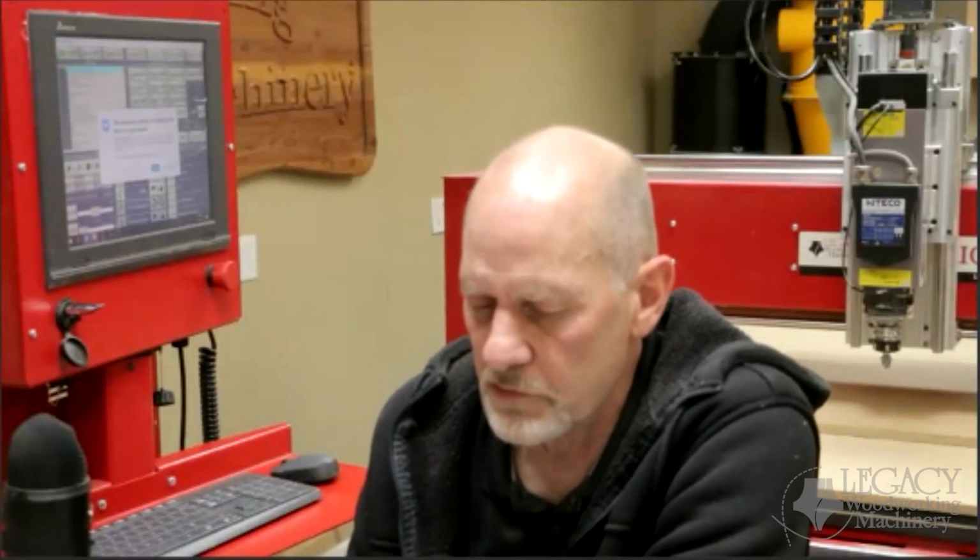The two things that you've got to do is the XY datum position, and the second one is the Z. If you set those two items up on your machine, you can run any program. And tonight we're not going to focus at all on the XY datum position. We'll worry about that later. Right now we're going to focus on just the Z0 position.